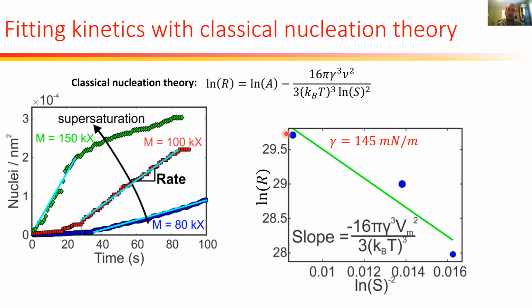And also we have this interface, which is silicon nitride. We're also knocking electrons out of the silicon nitride due to secondary electron emission, and creating vacancies inside the silicon nitride. That could possibly lead to, say, electron transfer to the interface, and that could also induce some nucleation as well. So think of that almost as an electrochemical process. Again, we can't model that, and the models just aren't good enough. This is kind of the best we can do in terms of doing a quantitative study.